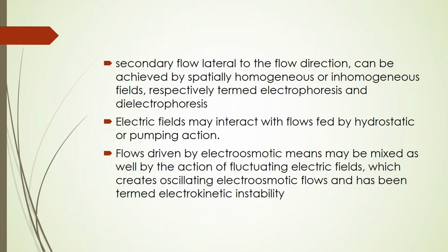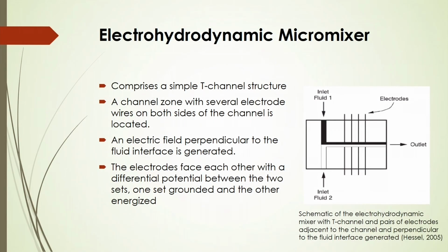Flows driven by electroosmotic means may be mixed as well, by the action of fluctuating electric fields which create oscillating electroosmotic flows, termed electrokinetic instability. So, the electrohydrodynamic micromixer is also one of the important developments of micromixers for intensification of the mixing process.